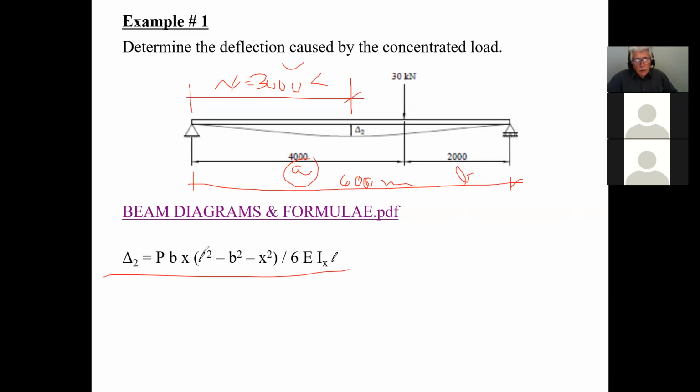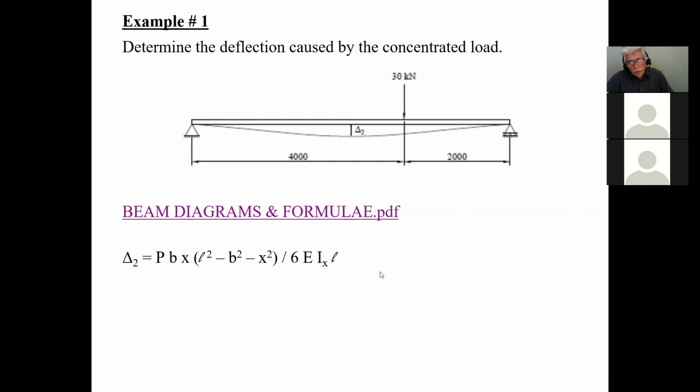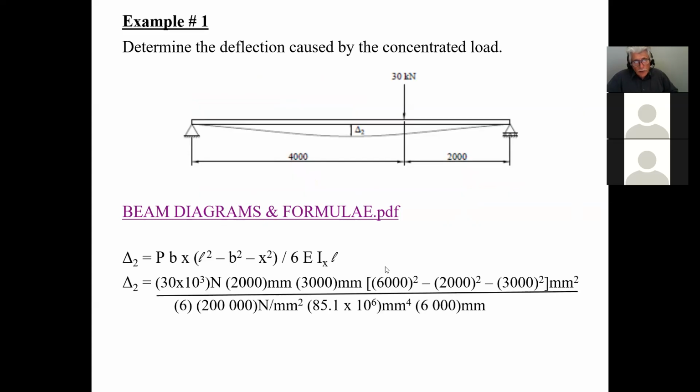So here's my x value. I'm okay. Now, the only thing you have to be careful about here, of course, is always the units. That's where people tend to make mistakes. You have to remember that this is in kilonewtons and this here is in newtons. So if I want to be able to cancel, I have to convert the kilonewtons into newtons, so I multiply by 1,000. Now, B, if we go back here, this was B. We want to calculate deflection here at a distance x from this reaction.